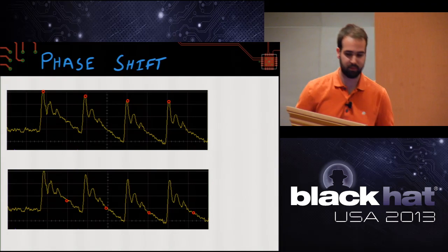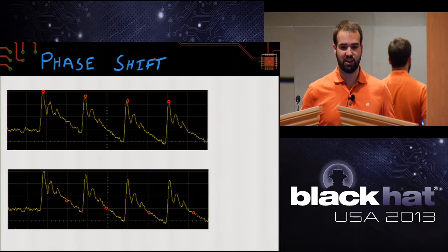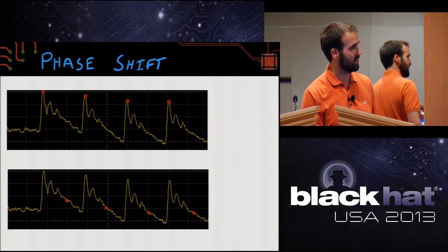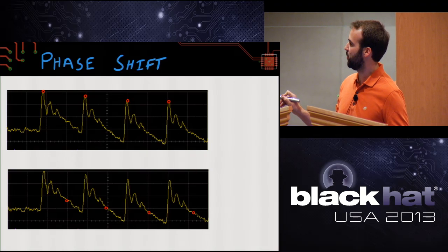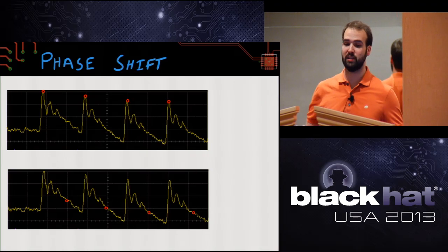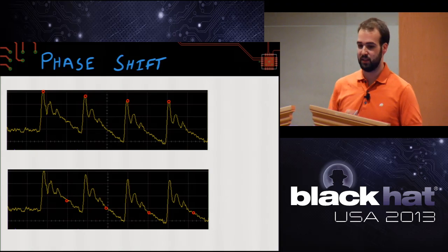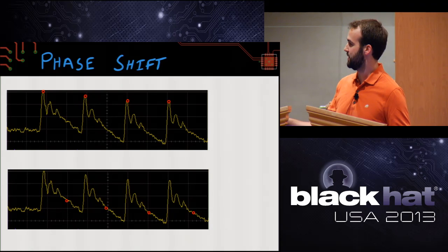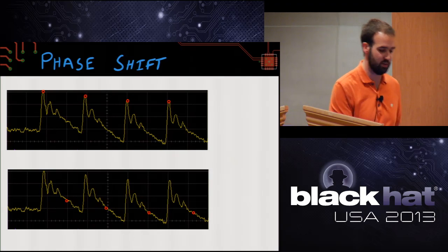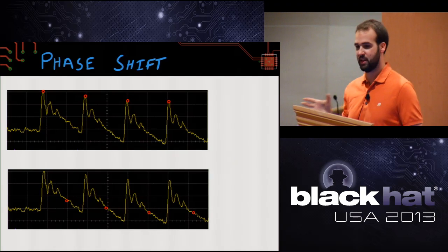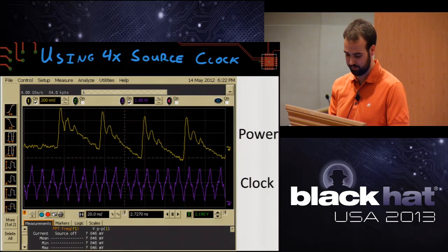The one small change when you're doing this with its sample clock is you need to be concerned about phase shift. So we can see in red there are some sample points, so I could say, well, if I could sample here, that's really good. It may be that because of delays in the system, I actually sample at the 0 crossings and I really don't get any information, so this bottom one. So you need to be able to control when the sample occurred relative to the device clock.